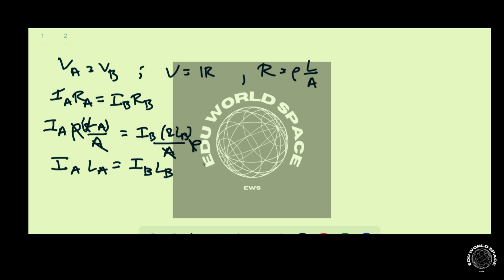And so we want to find how far the short is with respect to point A. We can eliminate LB by using L is equal to LA plus LB, which gives us that LB is equal to L minus LA. I can plug that in here for LB, so I have IA LA is equal to IB times L minus LA.